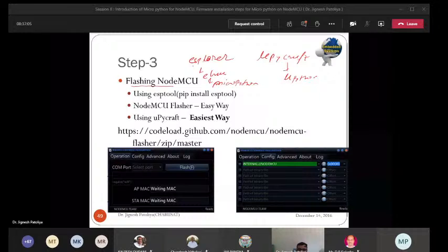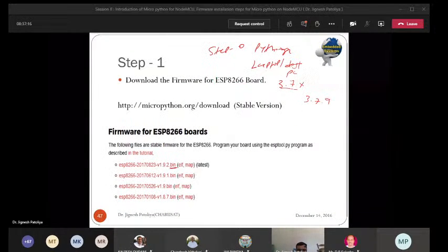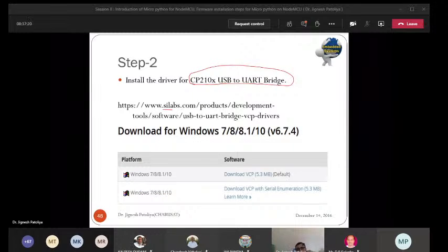So if again you want to explore the ESP loader, then first of all we have to install this firmware, meaning Python, in our small board. Meaning is that once you download this binary file from the internet, then we have to deploy this binary file inside this board, and for that purpose we have this small chip, that is the USB to digital converter, through which we can upload this program in our flash memory.